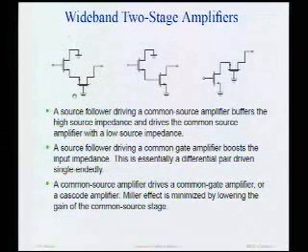Does this also look familiar to anybody? Is there a popular amplifier topology that essentially degenerates to this? What's that? Diff pair, exactly, a differential pair. Think about this as the common source node, right, going to ground. I've grounded one input, and I'm driving a differential pair single-endedly. And that's a very nice wideband amplifier topology.